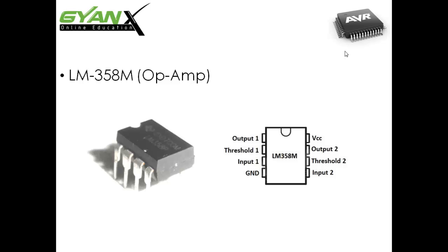If the parameter control voltage is higher than the fixed voltage, then the IC should give one output, and if it is lower than the fixed voltage, then it should give another output. So we see the IC gives only two types of output, which we designed to be 5 volt or 0 volt. This makes our sensor digital. That's why we are using the op-amp.